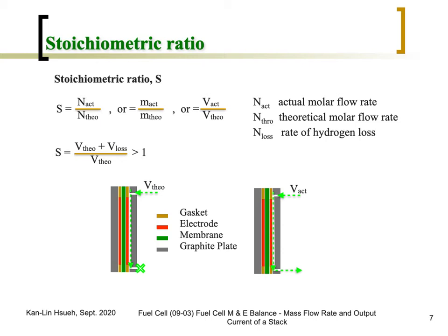So on the air side, the stoichiometric ratio is usually kept at 2 to 4, greater than theoretical consideration. So make sure you have sufficient air, the oxygen concentration in the cell stack. Also, the air is kind of free, so you can give a little bit more without any problem.